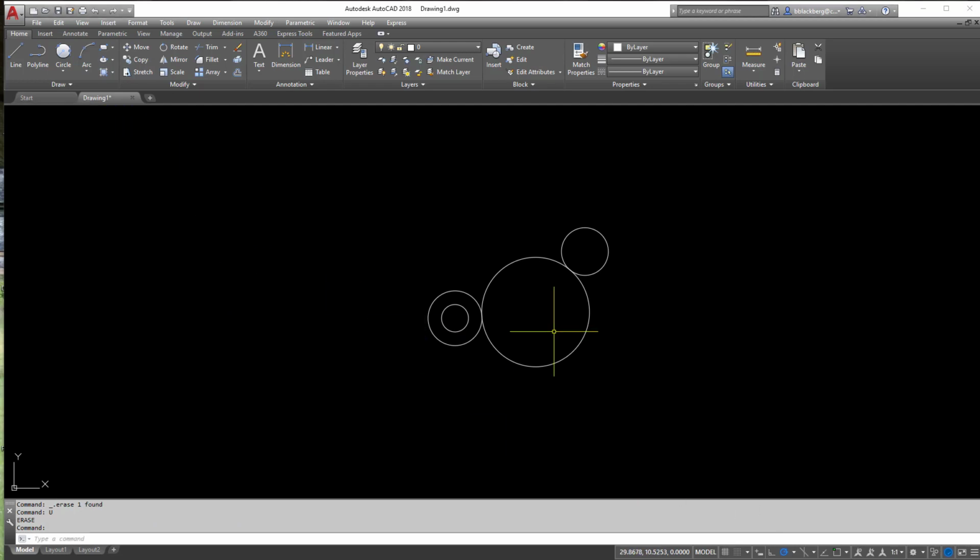Now the best way honestly is to get some drawing practice and to draw some items. I will try to link some quick drawing practice things at the end of this video. Feel free to give them a try. I'll give you guys some PDFs of those items to draw. Again, the more you draw them, the better you're going to get. And draw them multiple different ways. Try using dynamic input. Try using polar. Try using the old school method if you want. I mean, if you really wanted to, set the object up at 0,0 and use coordinates to draw the whole thing. It's really up to you, but find what works best for you and practice. That's the best way to draw things.